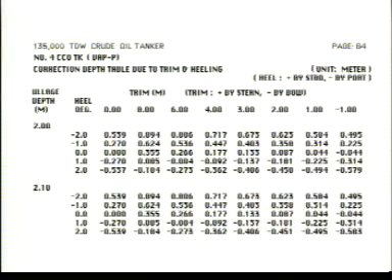This is the correction table for cargo tank number 4 and the port measuring point. At even keel and with no list, the correction is 0. Starboard side always has a correction. In this vessel, it is more convenient to take ullages on the port side. Let's work with our ullage of 206 centimetres and the given trim and heel. Interpolate between 200 and 210 centimetres, or 2.0 and 2.1 metres, as shown.